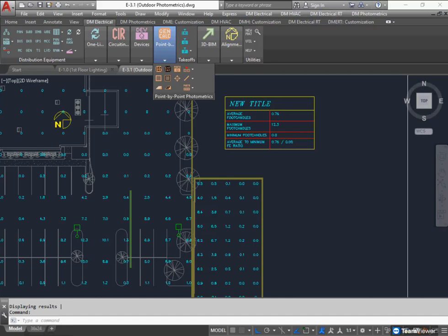All of this so far has been done on these flat areas. We also have the ability to insert a sloped area. This can either be a slope if it's actually outside and there's a slope. This is also how we recommend that you model stairs. So if you have a stairway in your building and you want to know the light fixture level, the foot candle levels on that stairway, rather than modeling each stair tread, just model it as a slope. And for your foot candle calculations, that's going to be sufficient in most cases for knowing if that stairway is lighted well enough or not.